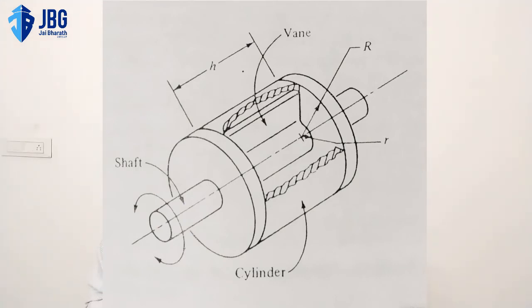So these are the two types of actuators which provide active motive force to the robot joints, that is pneumatic and hydraulic. There is one more left, that is electric. In electric, we classify it into DC as well as AC servo motors and stepper motors, which we will see in detail in the next class. Okay, thank you.